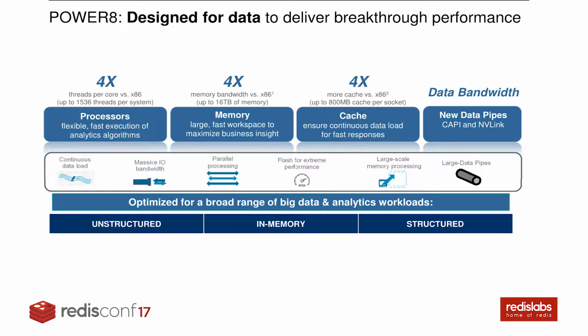We actually changed the way we were going to memory and run in 2 different modes where we have what we call a split memory controller on Power 8. In the past, the memory controller was in the processor. It was a separate chip. It was in the processor. It bounced back and forth for years and years. We actually have a split design. The reason for the split design was twofold. Number one was bandwidth. We can drive a lot more bandwidth, and it added an additional layer of cache.